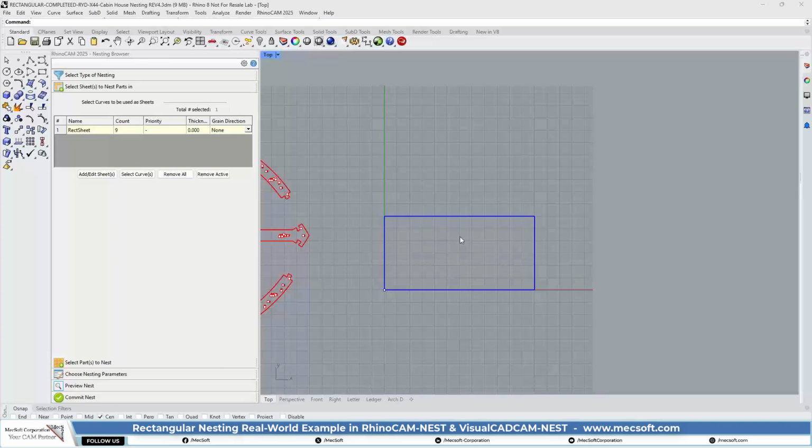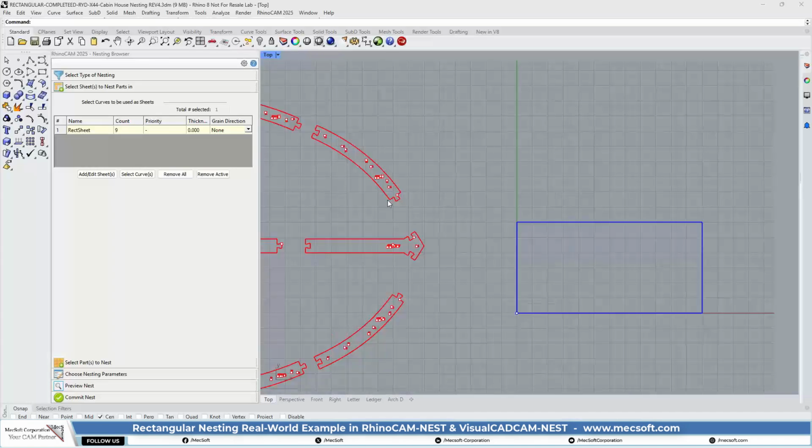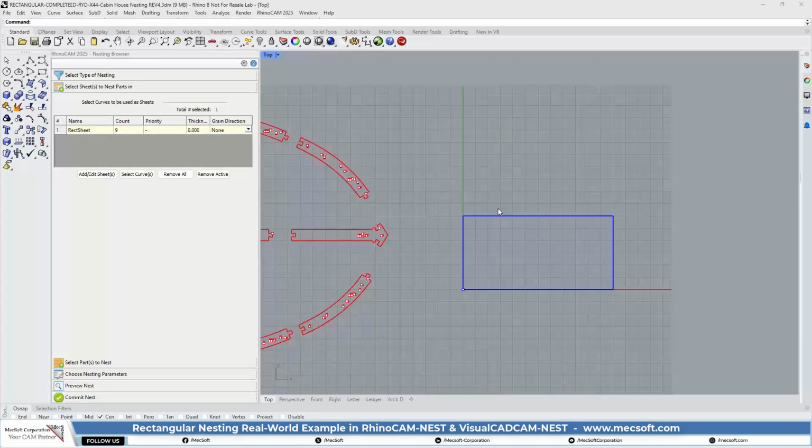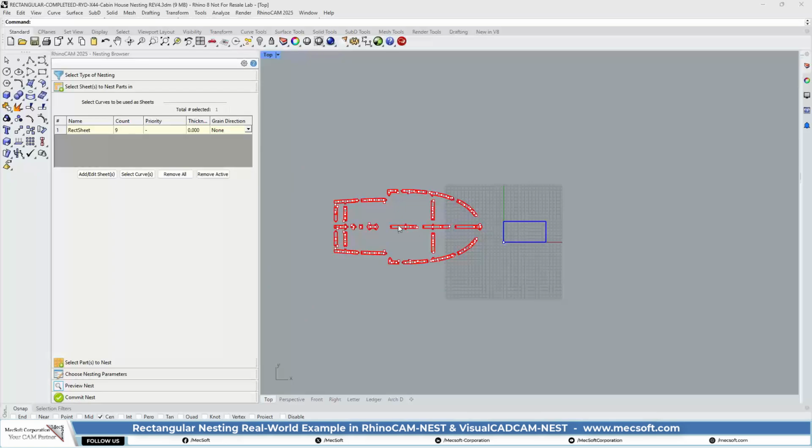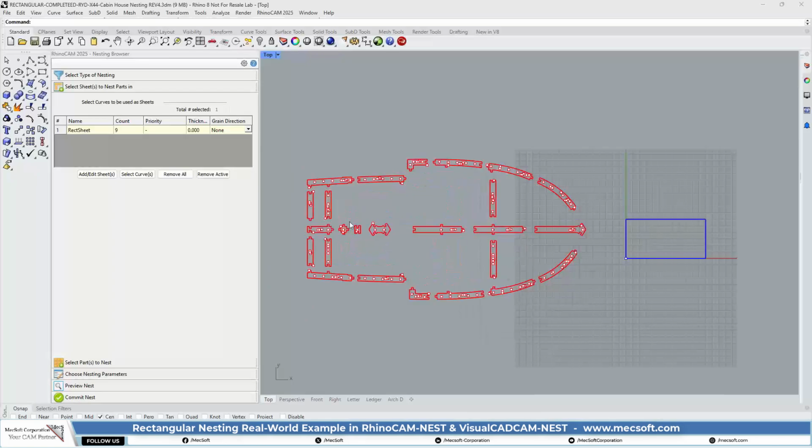And when you come back later, you want to run some smaller parts, you pull up the production drawing, you'll see what the remnant label is. You go to your stock, find the remnant, put it on the machine, and then you can use it. So that's kind of an optimum way to do it. Because if you're running a lot of these things, you're going to have a lot of remnants. You may not use them immediately. So you may want to put them back in your warehouse, but just make sure you label them on your production drawing.